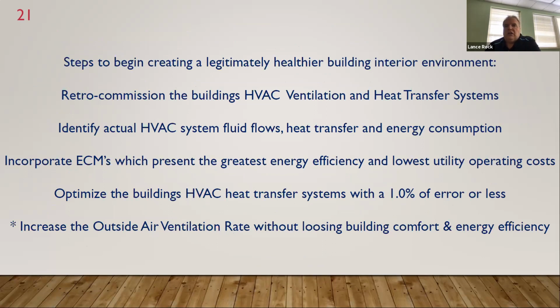Steps to begin creating a legitimate, healthier building interior environment: retro-commissioning the building's HVAC, ventilation, and heat transfer systems. Tom already touched on that. Going back in and actually looking at how we're operating and how we're filtering. Identify actual HVAC system fluid flows, heat transfer, and energy consumption. Incorporate ECMs, or energy conservation measures, which represent the greatest energy efficiency and lowest utility operating cost. Optimize the building's HVAC heat transfer systems to within equal to or less than 1% of error.